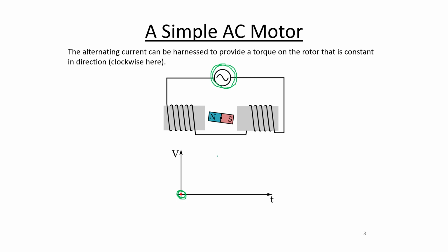Right? However, if we play the tape forward a little bit, so that we are farther up the input voltage, so we've got voltage versus time here of the AC source. And if we play that forward just a little bit, so we're coming up the side of the curve, say we've gone through about 45 degrees of the whole sinusoidal oscillation, maybe a little more. And that corresponds, as it turns out, with this so-called synchronous AC motor to about 45 degrees of mechanical rotation of the rotor.